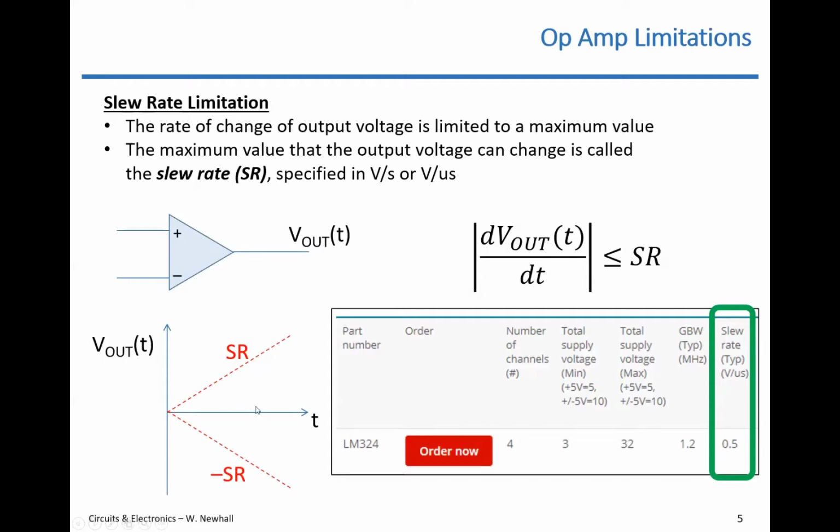Right? So you just take the derivative of sine, get a cosine, and figure that out. But slew rate relates to how steep a slope change you can have, and how high of a frequency you can have at the output of an op amp. Okay, so those are the common limitations of an op amp that really appear in most designs. You have to know, well, I want an output of negative 10 volts. You've got to pick the right op amp voltage swing. I need 22 milliamps. Well, you need to pick the right op amp.